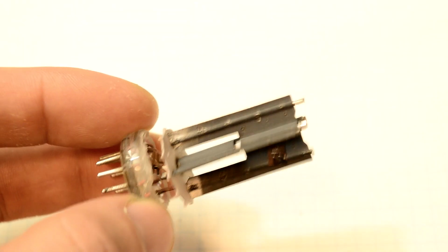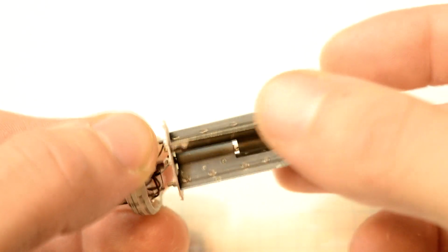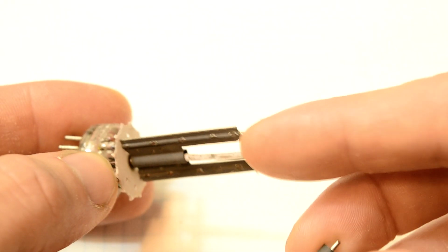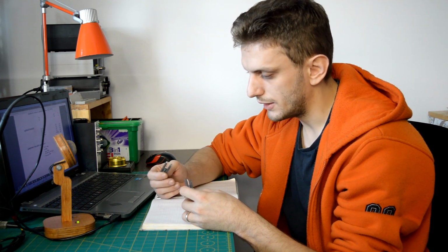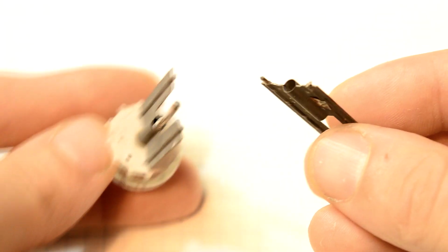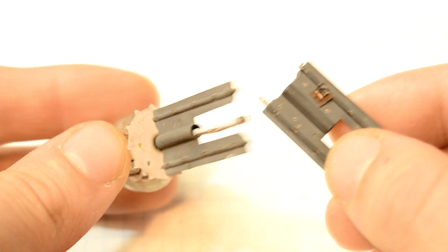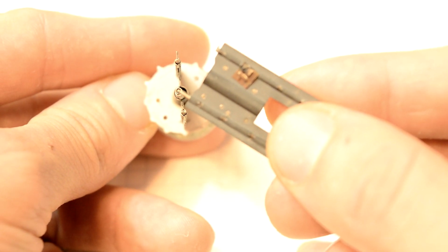So to clearly understand where these capacitances are coming from, we can look at how the vacuum tube is actually built. So you may remember this from my old vacuum tube teardown videos, and this is a double diode vacuum tube. We have the anode, we have the cathode, which is this tube, and then the filament is somewhere inside there. So the anode to cathode capacitance is basically the capacitance between the anode and the cathode, since these two are separated by a certain amount of space. And then from the cathode to the heater, we have a certain capacitance because, well, the heater is inside the cathode. So normally if you have a cathode separated from the heater, then you will have certain capacitance between the two. Now heater or filament, it's the same thing.